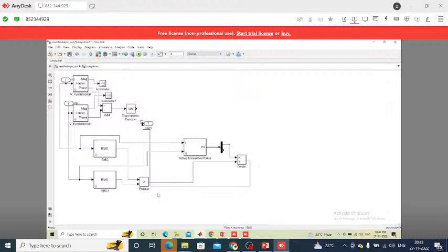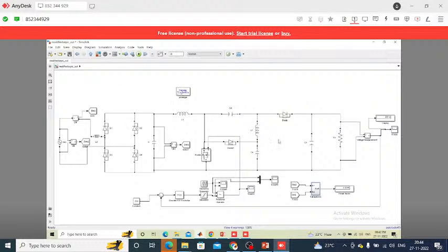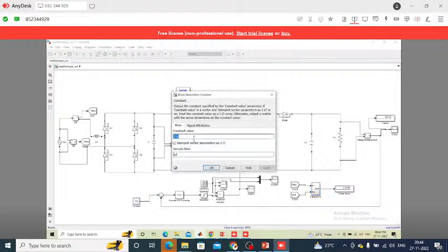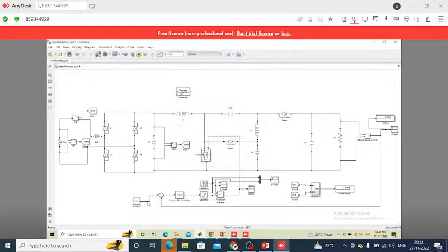After that product, I took another product, and I internally connected it to the RMS value. This RMS value is connected to the port input two and the active and reactive powers. It is a constant block. I gave it a value of 250. We will see the constant block. Here you can see the constant value is 250 and the sample time is infinity, and it is a sum operator.